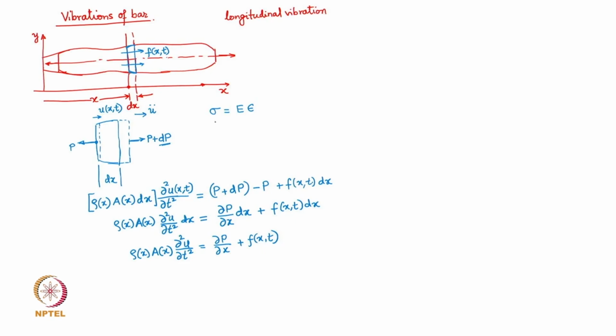What is the stress? That stress is going to be P over A(x), right? P at position x, and is equal to E(x), the Young's modulus, times the strain. How much is going to be the strain in this element?